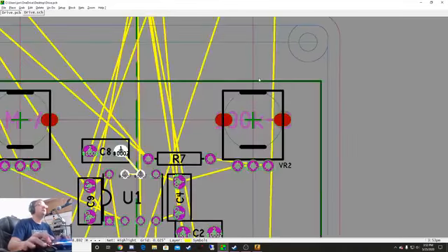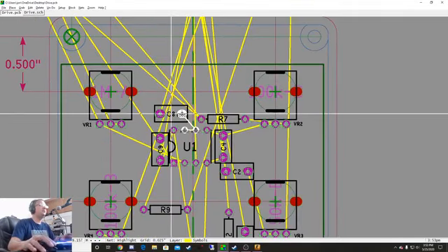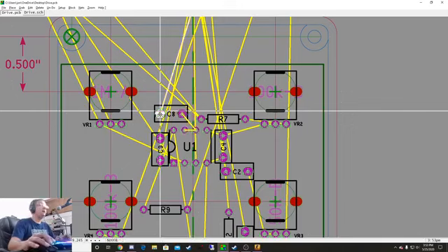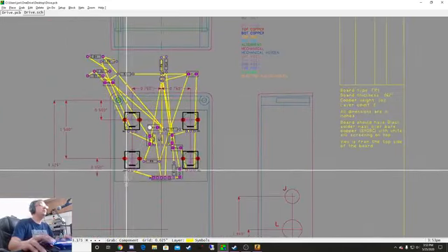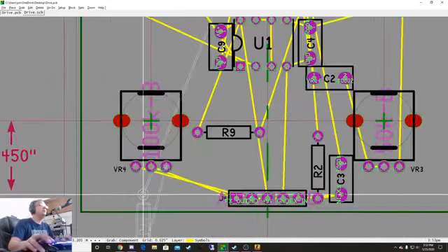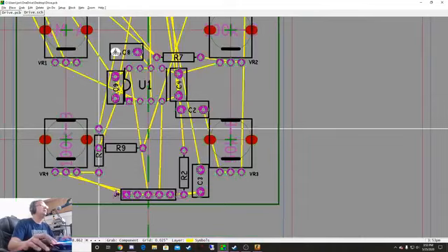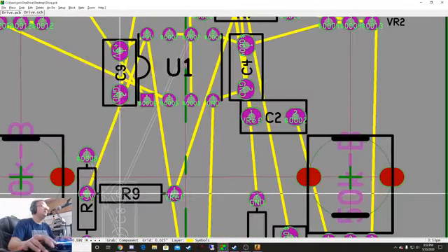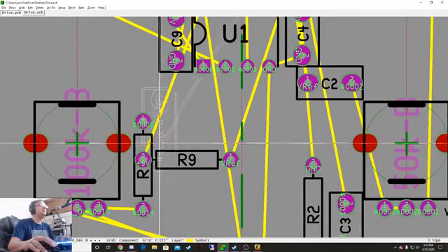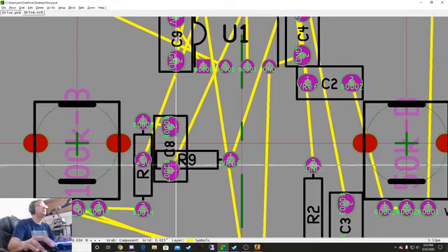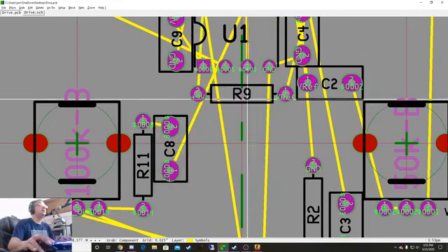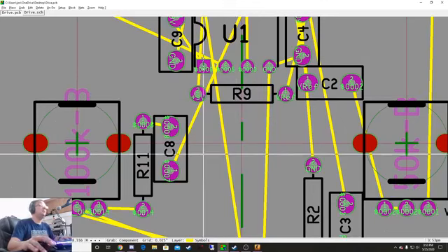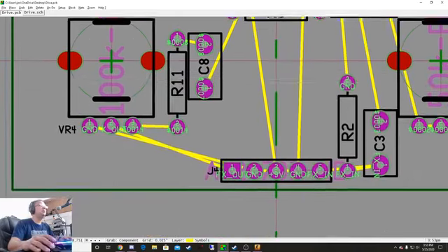So the reason I'm showing you that is because this part I know is going to the output pot. After here, I have a resistor, which is what's feeding it to the output pot. So what I would probably do, and we'll just start this right here and put this down here. So these are basically away from the op amp because it's, like I said, a buffered signal, so it can travel halfway across the board without creating a problem.